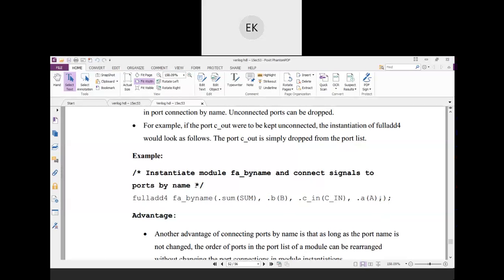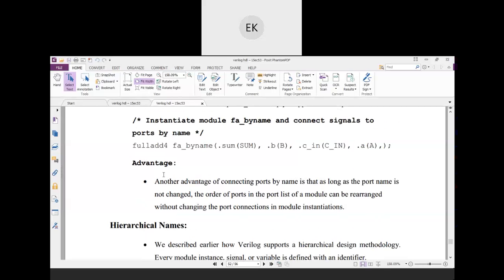See, the comma is there. After that, there is nothing. We ended with the comma here. After that, that is an open port, meaning one variable is not connected. If I don't give this comma over here, then automatically it will give you an error. Why? Because the full adder has 2 outputs and 3 inputs, totally 5 actually. So only 1, 2, 3, 4 will be there, so it won't match properly and automatically it will give you the error.